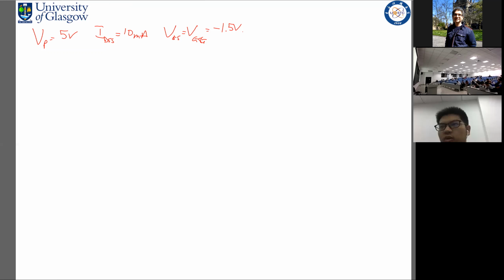First of all, we know from our expression that IDS is equal to IDSS times 1 minus VGS over minus VP, all to the power of 2.